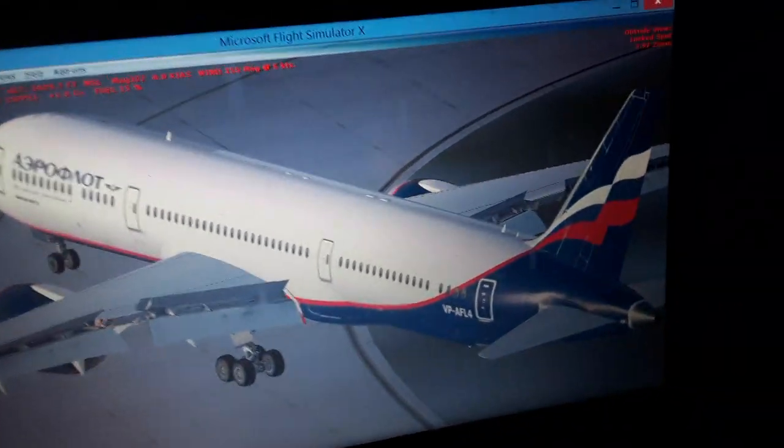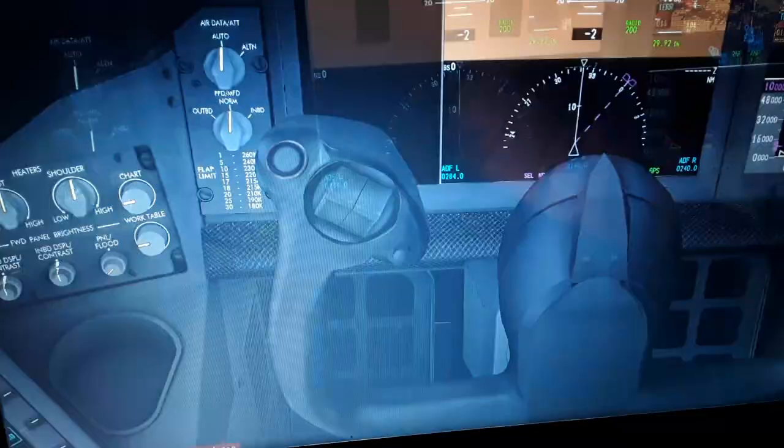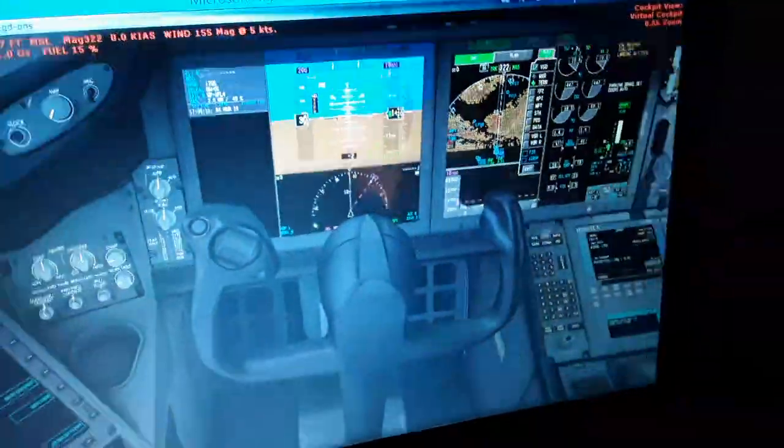Also, I'm gonna show you a little bit more of the flight controls. Also the horizontal trim stabilizer over here. So this is a fly-by-wire aircraft. We have the auto trim and the fly-by-wire channels, the normal, the alternate and the direct law of flying.